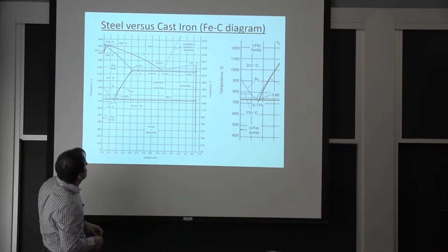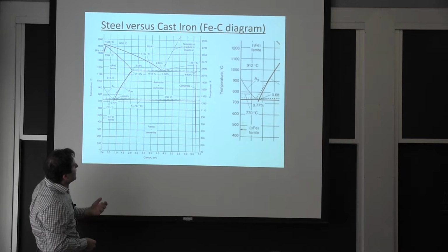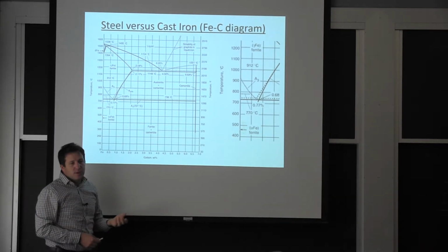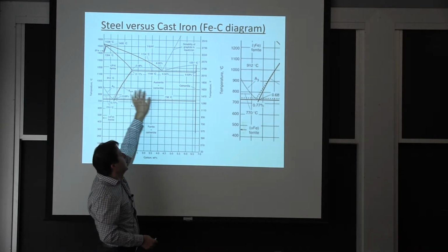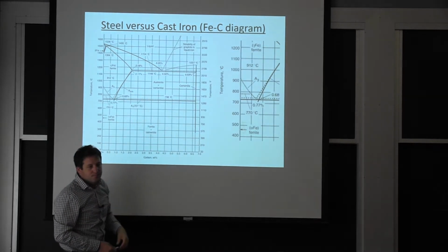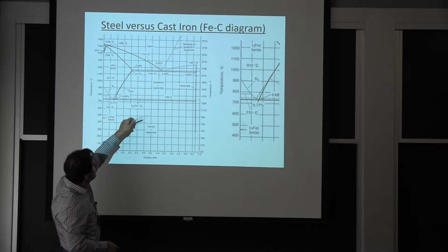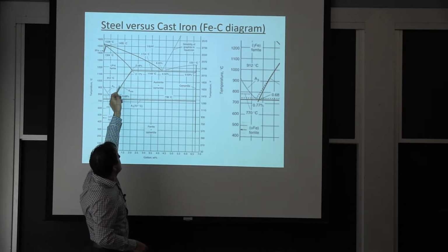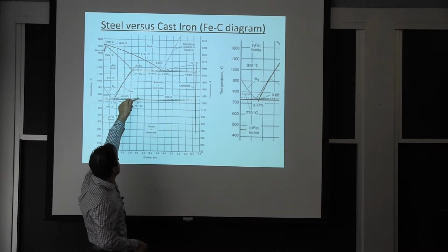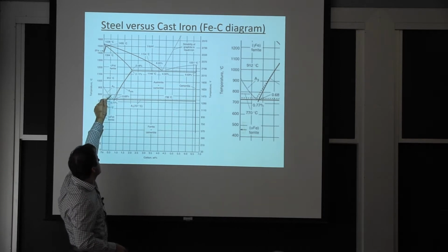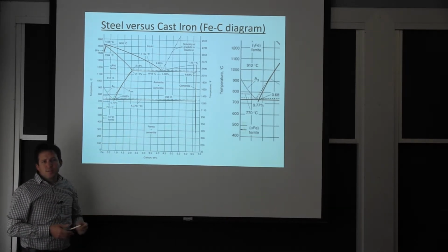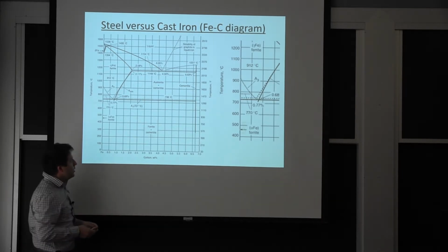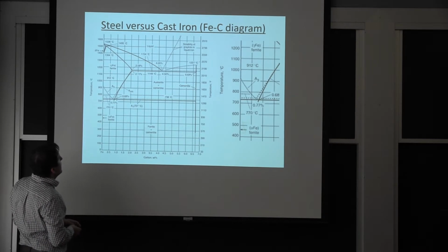Everything here is a lot of phase transformation. We're not talking about precipitation or hardening. We're going from a liquid into two different solids of two different compositions. And we can have extra transformation. So you form the austenite and the cementite. When you go to this temperature, you get an extra transformation in your austenite back into more phases. So these microstructures are very complex to look at. But they're very cheap to manufacture.